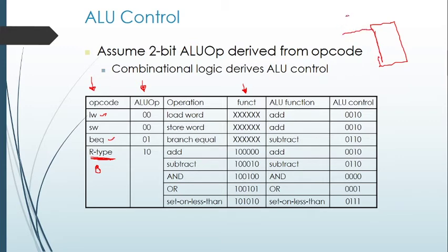This comes from the main instruction, and it generates a set of control signals according to the type of instruction it is facing. One of those control signals, called ALUOp, goes to the ALU control unit. So what happens in the ALU control unit?